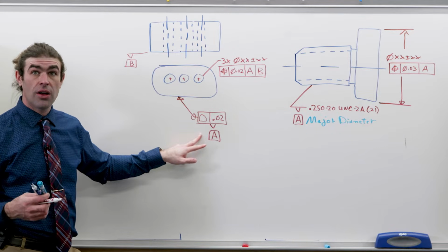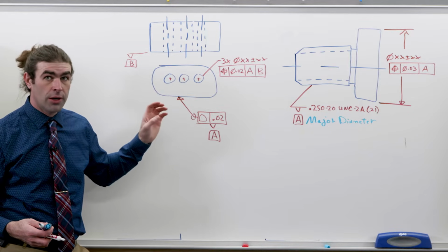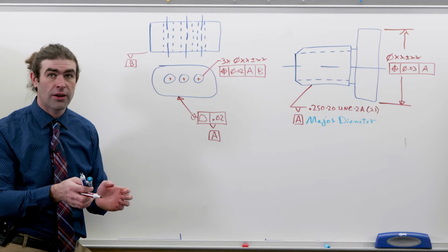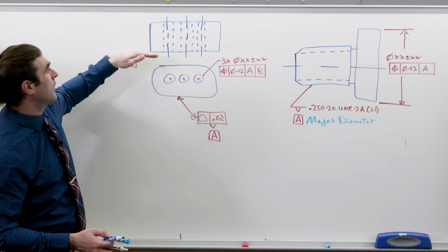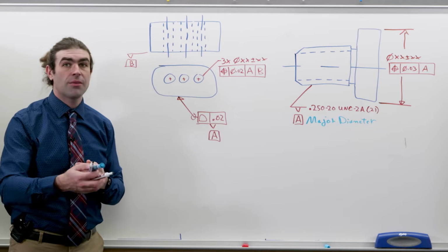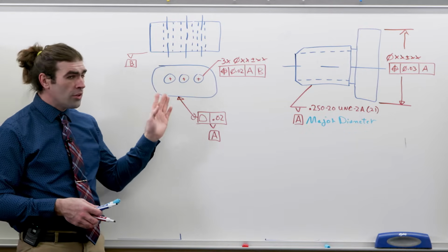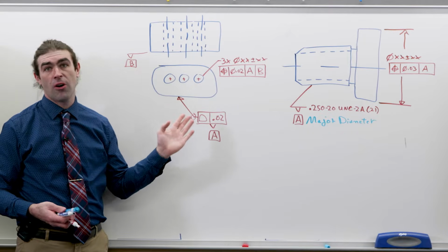This is allowed. So that takes away 5 degrees of freedom, right? Because it's a special shape, it can't move in any direction except up and down. So datum B is one of the top or the bottom of this part that locks down the last degree of translation. You probably wouldn't want to specify this as RMB or RFS though.